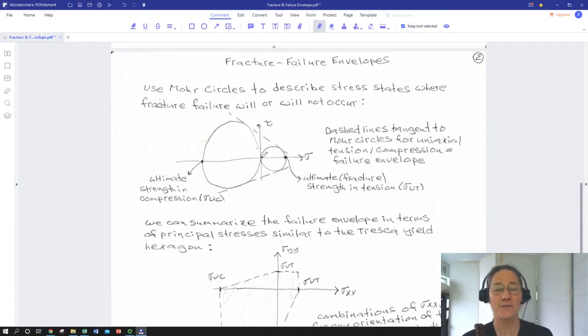So this small circle represents our material in tension, and this particular tensile stress corresponds to when it would have broken. Okay, so here's the corresponding shear, which is less important because we're not going to enable any deformation mechanisms, regrettably. And here's the much higher in magnitude compressive stress that also corresponded to failure.